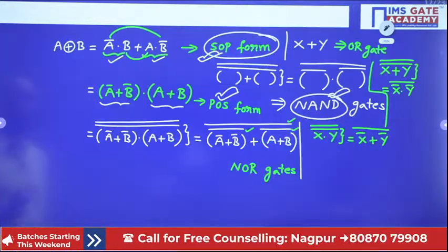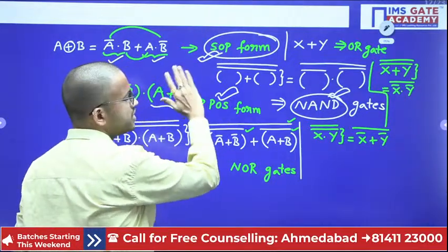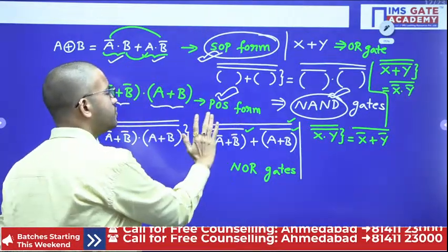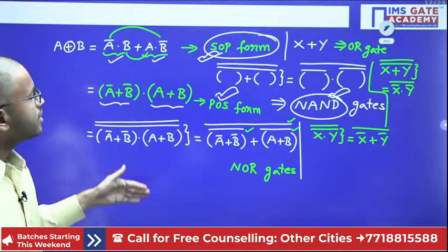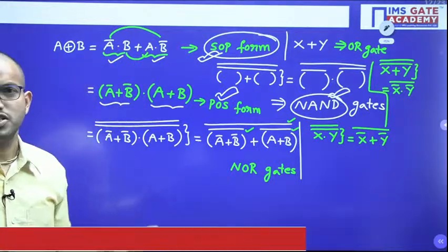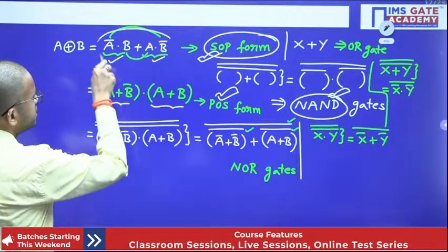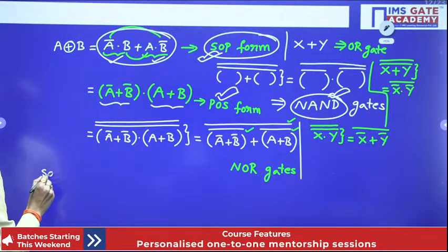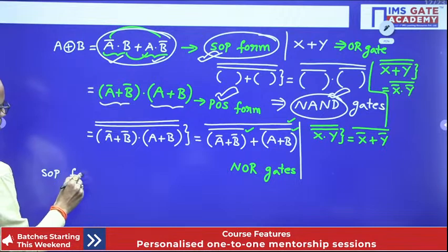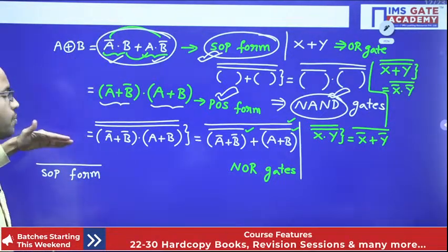Okay. So regarding logic functions, up to here what I have mentioned: if you are having SOP, you can easily implement it with the help of NAND. Similarly, if you are having POS, with the help of NOR. Since Ravi asked how to implement if you are having the complement version, it is very simple. Say for example, this particular function is in SOP. If that function is in complement form, then what?